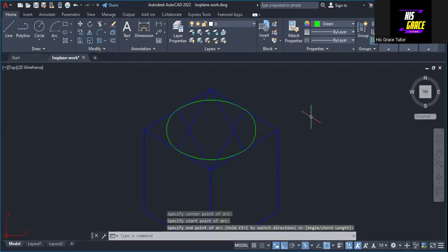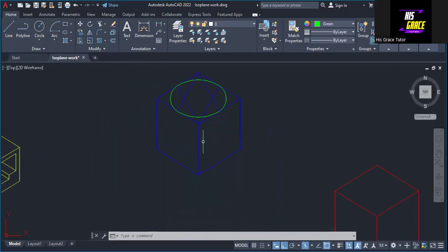We have this isometric square on this top face. Maybe we should just make use of this, because this is the right face and this is the left face. Let's make use of this isometric cube alone to do everything that we want to do. We want to draw an isometric circle on this right face now. Let's see what we are going to do. We are making use of this point and this point. This will be center 1 and this is center 2.